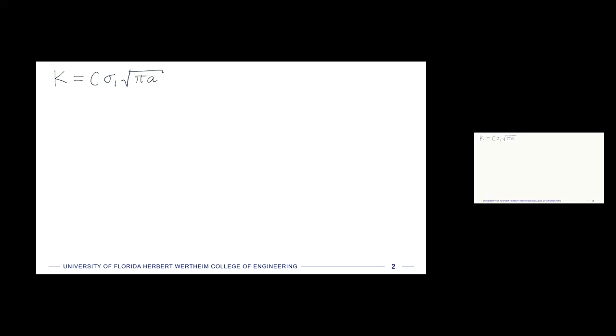We said we were going to use the uniaxial tension mode 1 crack opening as our most extreme case, so we'll stick with that today. Because of that, we'll be calling this K1, for mode 1 crack opening, which was that Pac-Man situation where there are forces directly pulling the crack open. And then we'll have a geometry factor based on that, and the same, our stress times the square root of pi times the crack length.